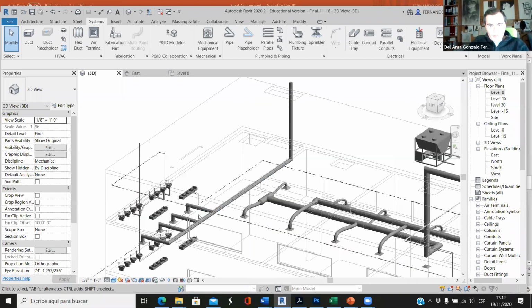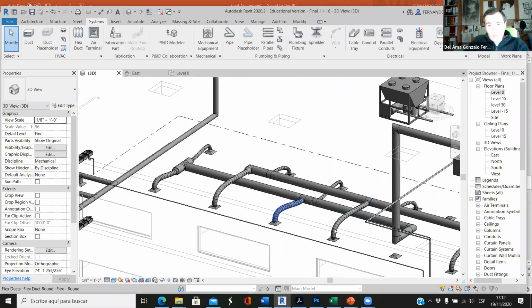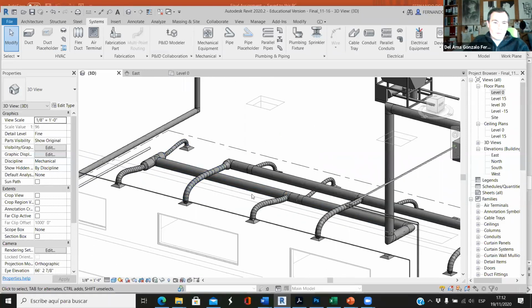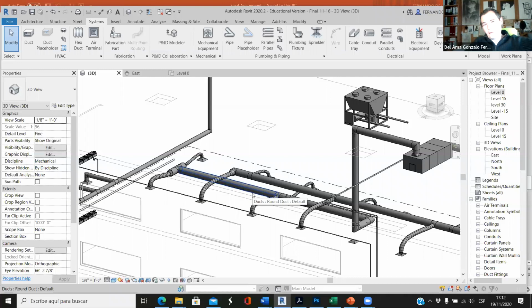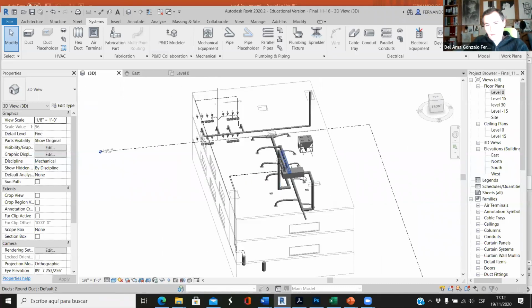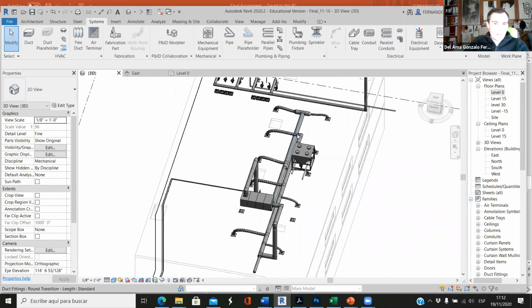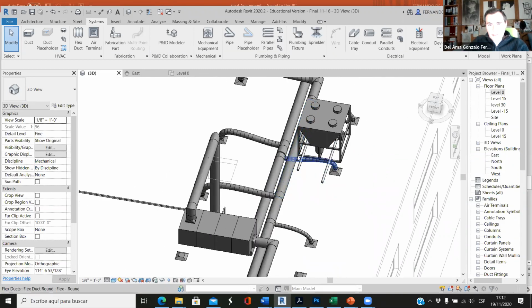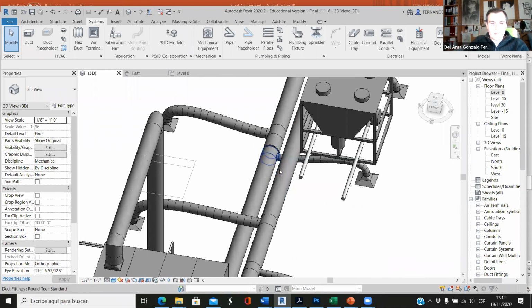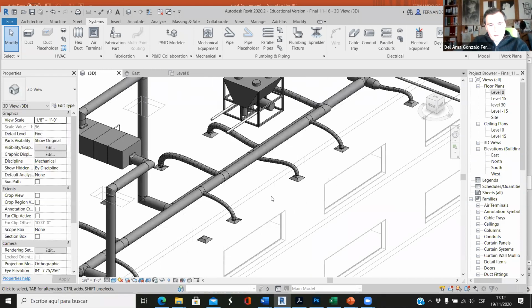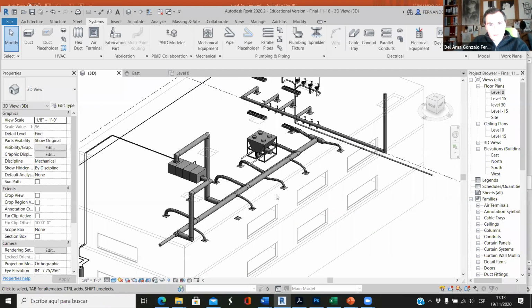Okay, so I wanted to show you this, and then I wanted to show you how to deal with that. In the first assignment, we had like a supply duct in this side of the building, a return duct in this side of the building, and we didn't have any conflicts. But when we have constraints, usually those elements, those ducts, are along the corridor. And well, if we have this, we have to make sure that there is no intersection between the supply and the return. Okay, so this is the lesson.